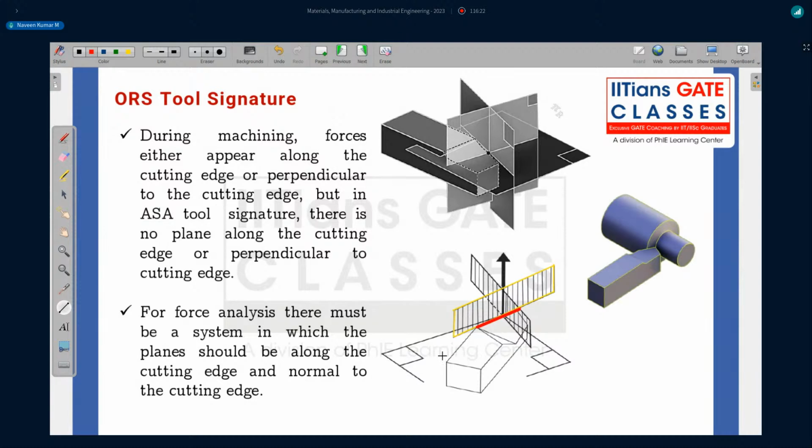That is your side cutting edge. And that plane is not orthogonal. Sorry, it is called cutting plane. I just used the wrong notation, I'm sorry for the earlier statement. I'll take it back. This is your cutting plane, pi C. And perpendicular to that plane is called the pi O plane, that is the orthogonal plane. Cutting plane, orthogonal plane. And this plane is pi R plane as it is. We are not going to change that reference plane pi R.